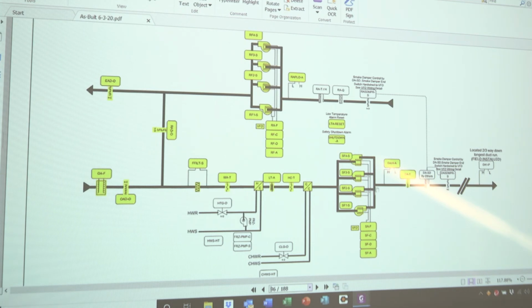Speed commands, safety switch, discharge air temperature, smoke dampers with end switches, controlled by pressure downstream 2/3 of the way. Returning back to the unit, smoke damper with end switches, flow station, temperature, humidity. Through the fan section, you have your safety control, low suction, this protects your system, and will trip on low static.